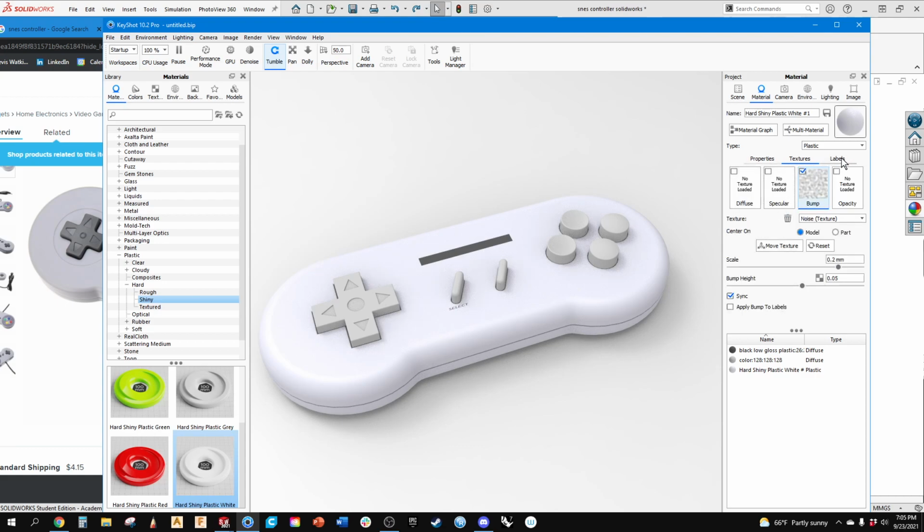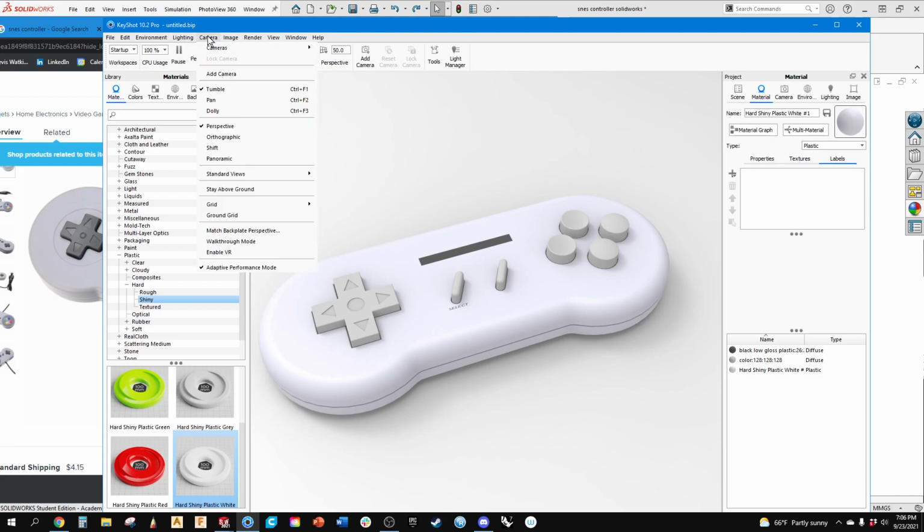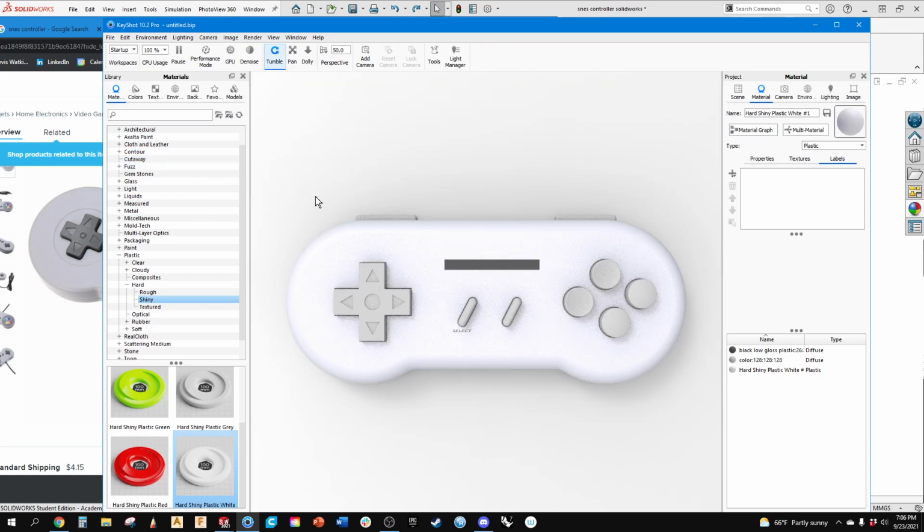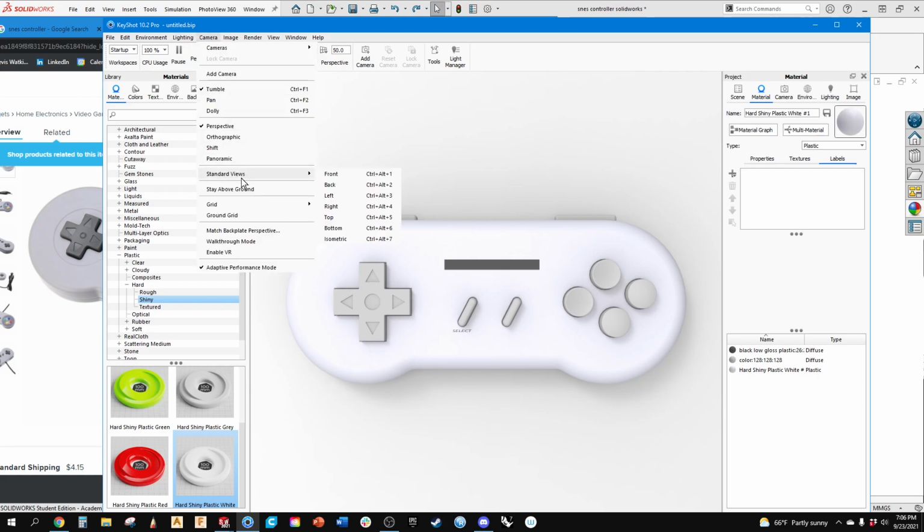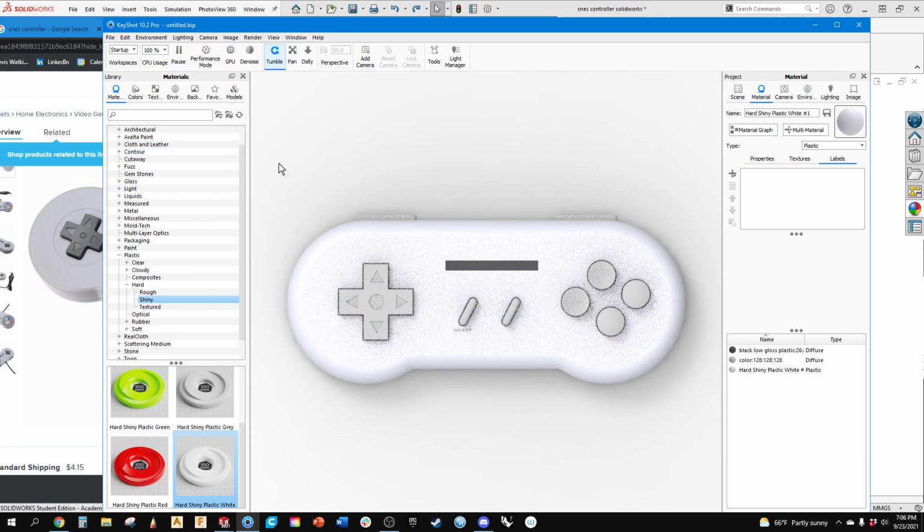Now what we can do is labels. Labels are exactly that, they're graphics. So what we're going to do is start and go to a top view. We're going to camera, standard view, top. Again, you did a great job of setting up the shaders, or the planes, so that when you go in another software package, it makes sense. Then I just like to make the camera orthographic.